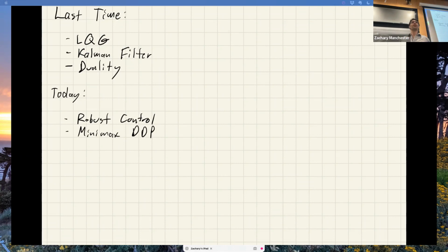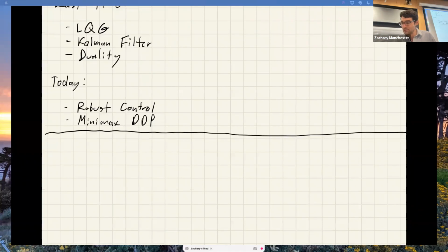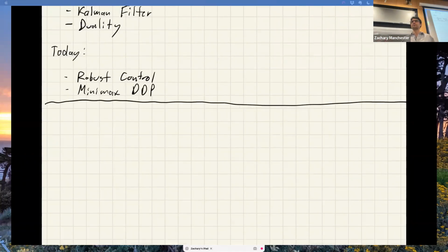There's a really fun quote that you can solve basically every problem in control with LQR. This is yet another example of this, right? Stabilization, tracking, trajectory optimization for nonlinear systems with iterative LQR. And it turns out that with another extension of LQR, you can do robust control. There's a Minimax LQR DDP type of idea. And also state estimation, right? The Kalman filter is basically LQR the other way around, so you should really spend some time with that one. It's a really powerful idea. All right, cool. Any questions about any of that?